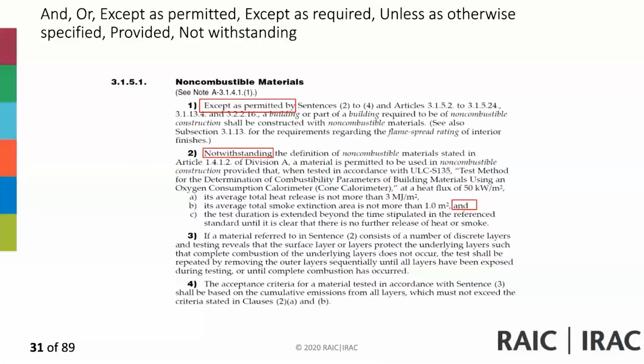Okay, so where you looked for non-combustible material is on page 1-9. It's in the definitions, right? Why is it in the definitions? Because it's in italics. It's a defined term. Non-combustible is a defined term. If you look at the definition, as you just said, it's a material that meets the acceptance criteria of CAN/ULC S114. So a non-combustible material has to pass the criteria of CAN/ULC S114.